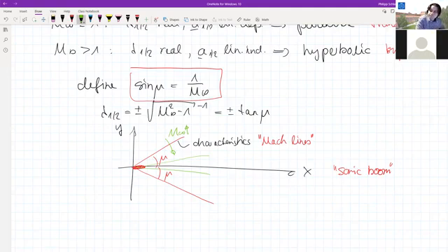But that also means that if you go in the other direction, the Mach number goes lower and lower. At some point, you will reach 90 degrees with mu, and that, of course, is reached if the Mach number is 1. Then the Mach lines are vertical, and that exactly corresponds to the fact that the slope becomes infinity.